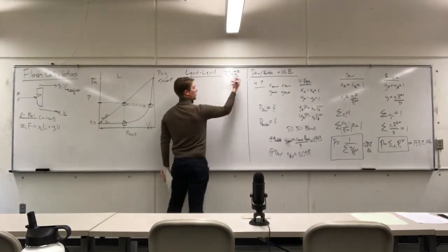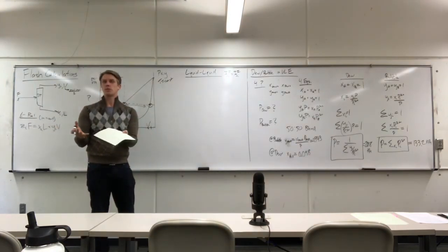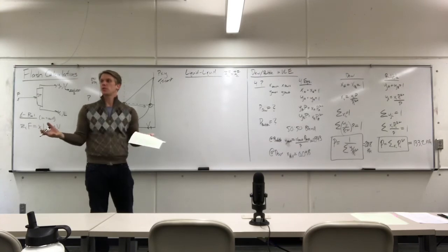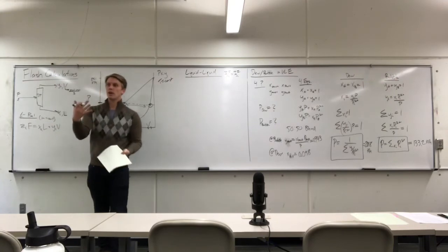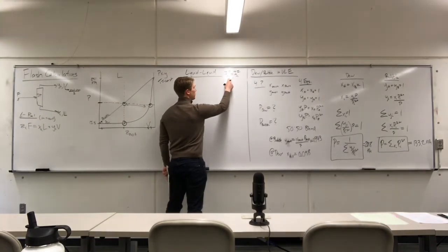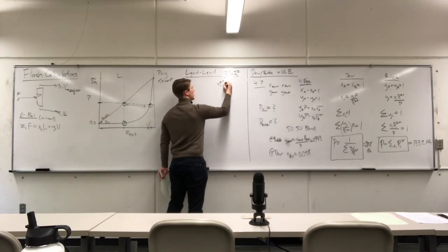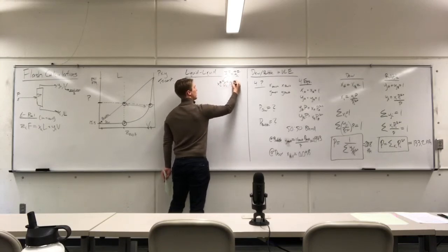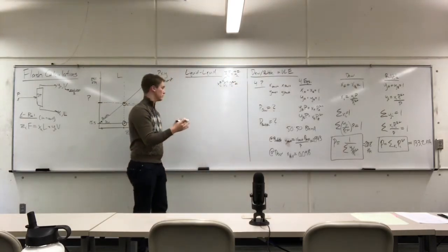Now, when it comes to actually substituting this in, the laws that we've learned still apply. We still have the fugacity of a vapor, or potentially we still have the fugacity of a liquid. Those expressions are completely assumption-free. The fluid doesn't know what kind of phase equilibrium it's undergoing. All that we know is we know how to calculate the partial fugacity. So for low-pressure liquid-liquid equilibrium, we oftentimes write this as x of species i in phase 1 times the activity coefficient of species i in phase 1 times the saturation pressure of species i, which is going to be constant across both the phases.